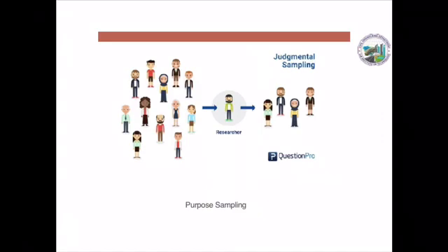When any sampling method is done, we usually have error because we are just taking a representative of the entire population and concluding the characteristics for the entire population, which gives us a lot of error. So as far as possible, when transportation planning surveys are done, try to have a large number of sample units so that the errors can be minimized.